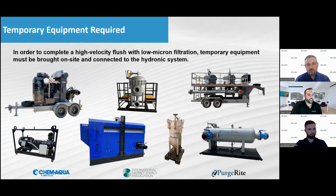In order to complete these high velocity flushes, these are some of the components that we deploy, just to give everybody a visual. So we bring in external pumps. If you're doing a 24-inch chilled water line, let's call it carbon steel, or a heating water line, what we put together in our systems, and what a mechanical contractor would try to rent or cobble together, but it's difficult, is first of all, pumps that are capable of moving the high velocity and high volume of water that you need.